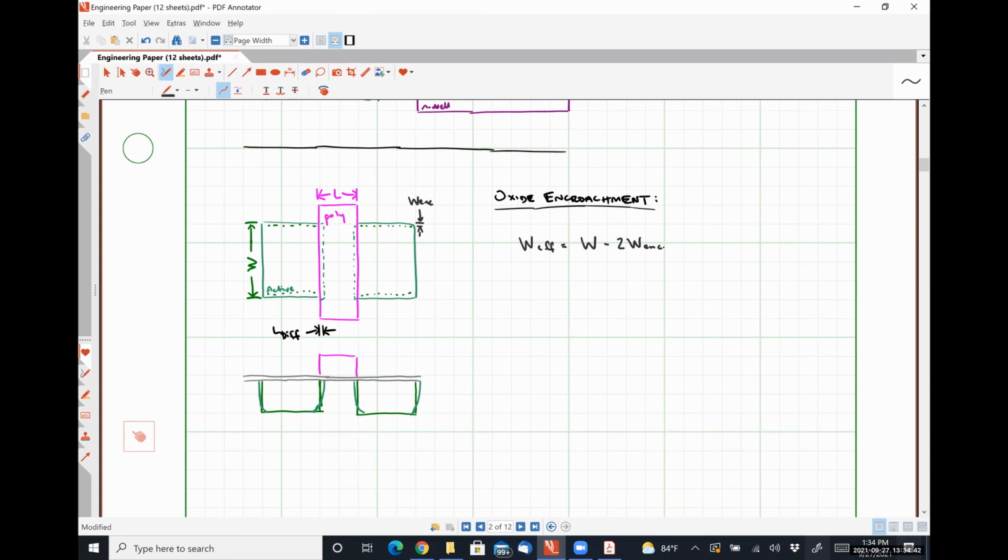So this lateral diffusion and these oxide encroachments can skew that current-voltage relationship ever so slightly. In a digital circuit, it doesn't particularly matter. In an analog circuit, as long as we don't let things get wildly out of control, that's really not going to make that big of a difference either way. We're talking about a channel length where, in our C5 process, the minimum length of the gate is 2 lambda, that's 600 nanometers. We might be dealing with 595 nanometers instead of 600, stuff like that.